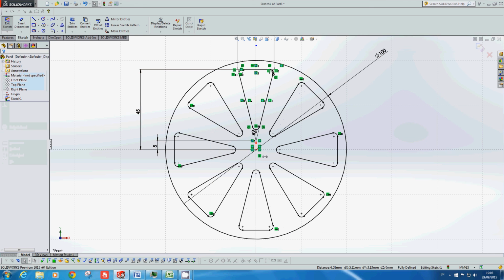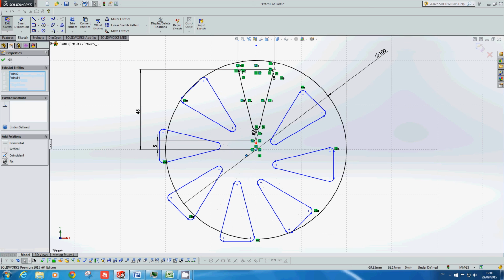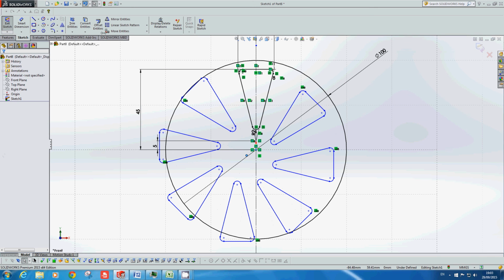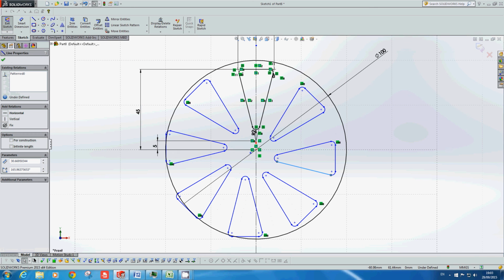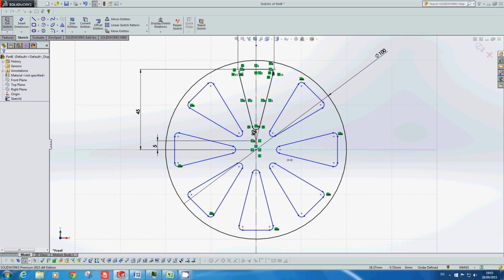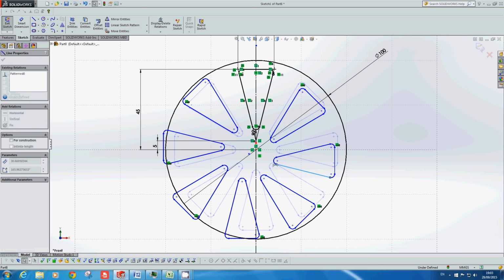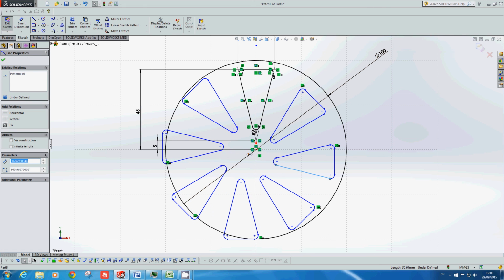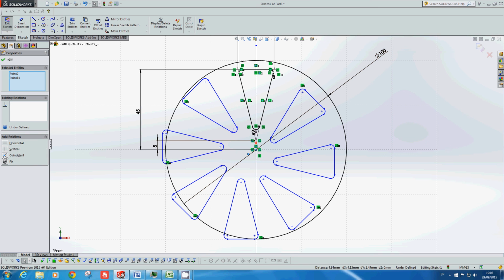And also, when I see that highlighting there, I'm just going to do that once more. Undo and undo, and just undo once more so that it's there, right? Okay, so just click and pull it away so that I can see the point. Click the point, click the origin, and you're clicking coincident. Now see this fixed constraint, don't use it.